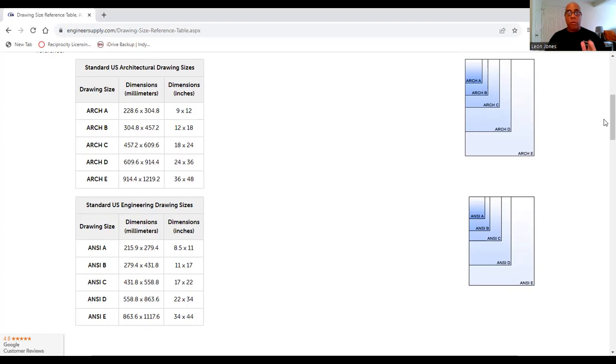And what you have to do is look at the type of paper where you're going to get full scale. You're going to hear half scale, full scale, quarter scale. So basically 1:1 is what we call full scale. So the largest sheet of paper is going to get you your actual scale. But most of us in the field, we use a half size. So that means everything is going to be reduced in half.